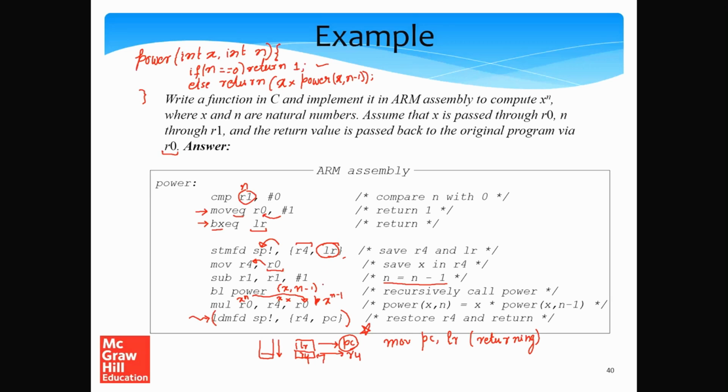But now when we are returning, there is no real justification of actually restoring LR, because in any case it makes little sense to restore it after the function has returned. What we instead need to do is effect the return. So we pop the value of LR, but instead of saving it in LR, we save it in PC.